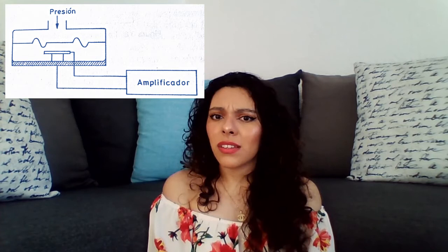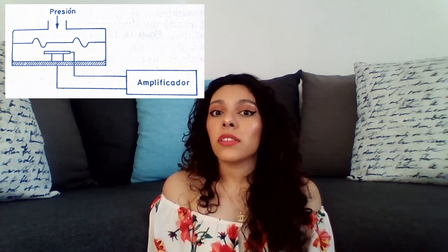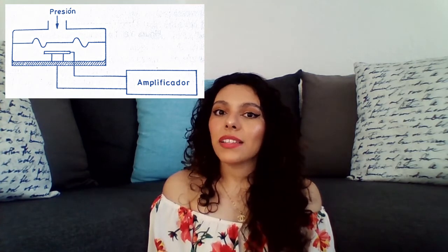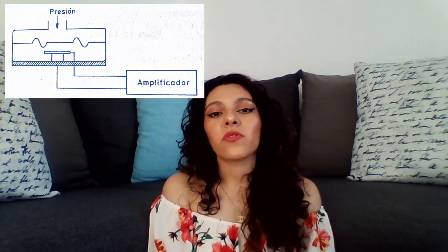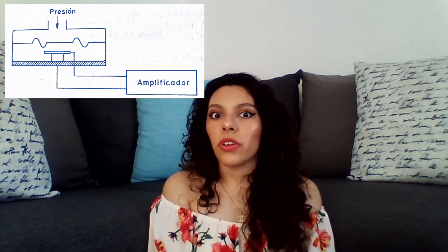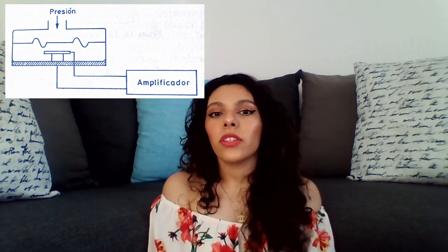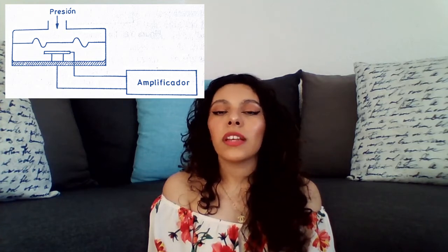Their disadvantages are that they are sensitive to changes in temperature, experience zero drift, and require impedance adjustments in the event of strong temperature shocks. In addition, their output is weak, and they need signal amplifiers and conditioners that can introduce errors in the measurement.